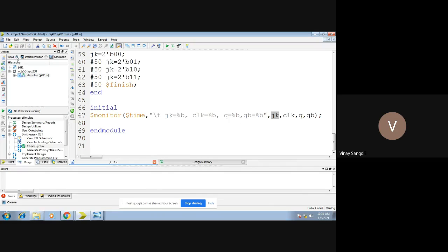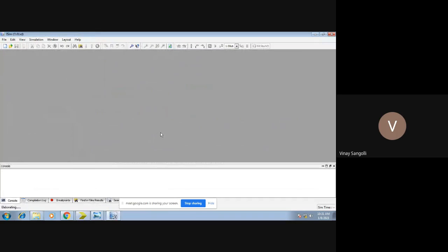So you know how to implement it. Click on implementation and do the check syntax. Go for simulation. Click on the top module. Don't expand it, and click on the lower module. Click on the top module. Then do the behavioral check syntax. Finally, simulate your behavioral model.